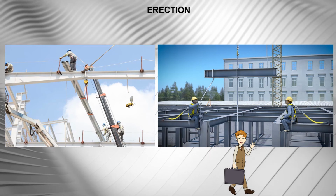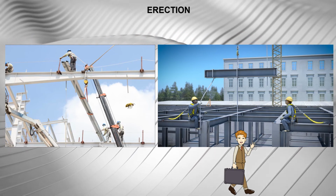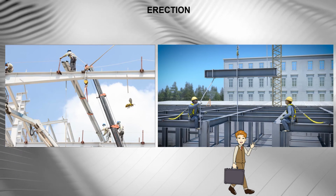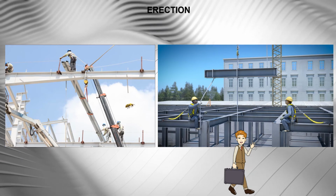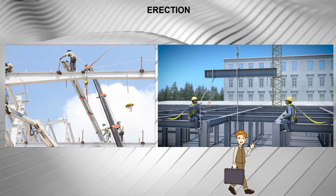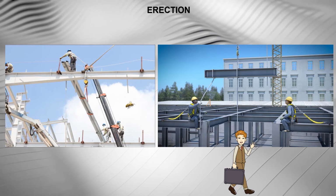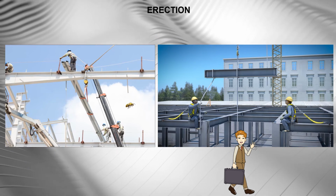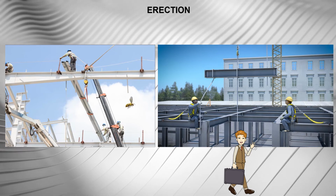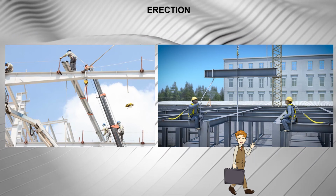However, since cranes are likely to be used, the effect of dynamic lifting load or stress reversal should not be ignored. All steel structures are likely to require temporary bracing, which may be part of the permanent system. The temporary systems need to be carefully designed. The following factors summarize the process.